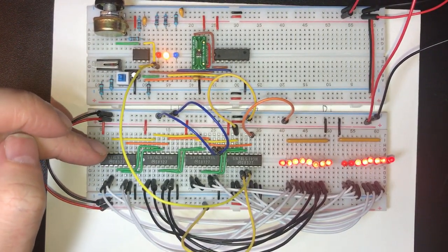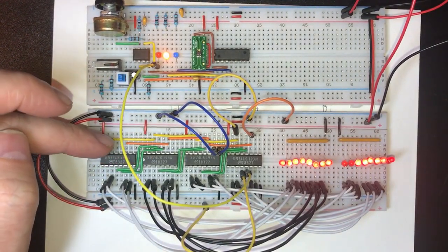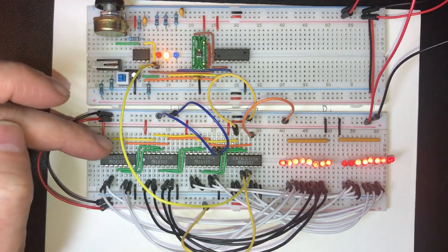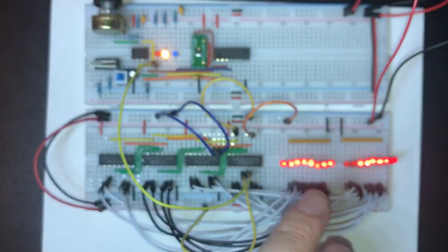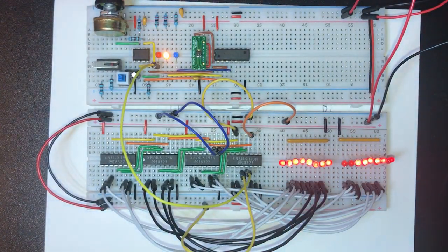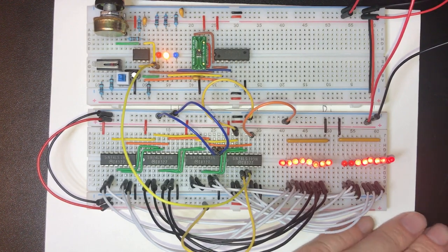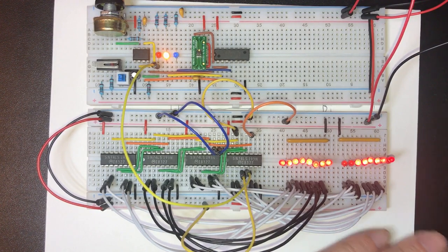Okay, so if we had all of these 16 inputs onto a bus, we could stick a value on there, momentarily drop this line low and load that value into here. So in the next stage, I will be looking at the ways of getting the values from here back out and onto the bus, and perhaps some of the more interesting timing considerations about that. But that's more than enough. All right, thanks for watching.